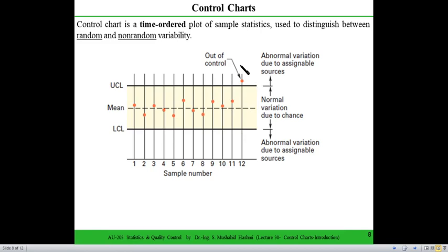And obviously this out of control process occurs due to some abnormal variations, or there is a certain reason associated. Maybe the operator has changed, or a new shift has come, or a machine has had an electrical power surge which changed the mean value considerably. In this normal range, everything is predictable and statistical. Once you are away from this normal variation range, between the control limits, there would be some special reasons for that variation.